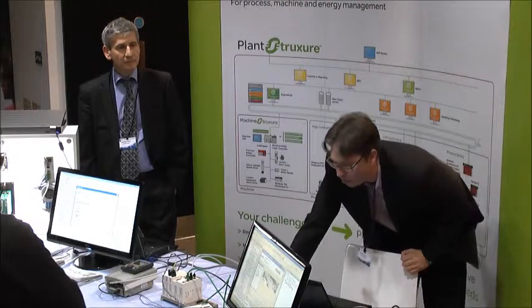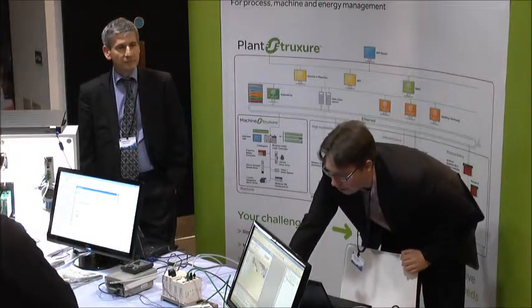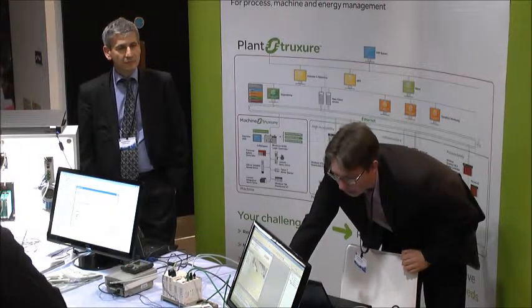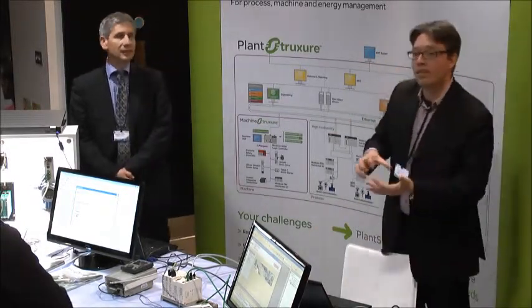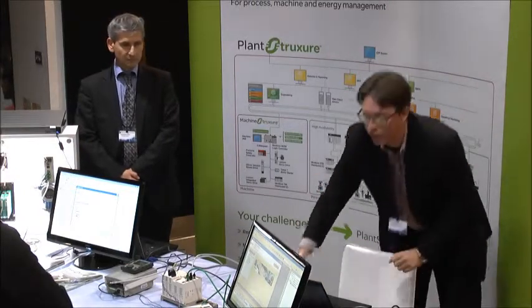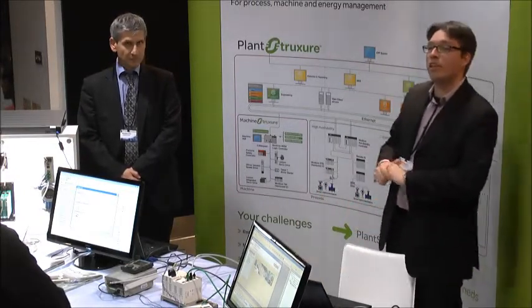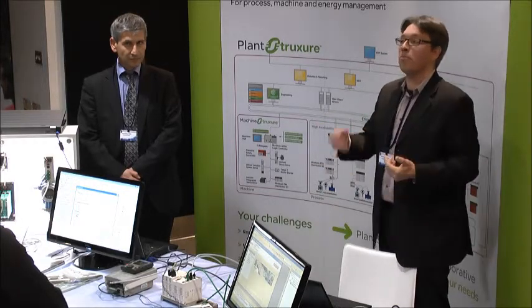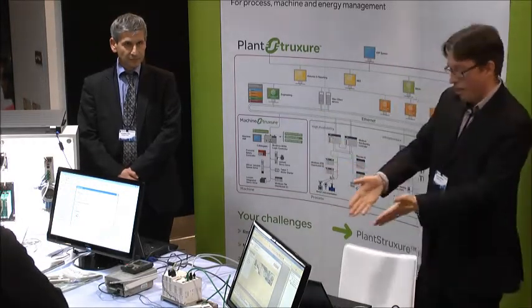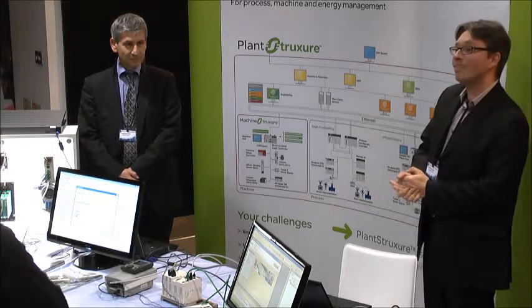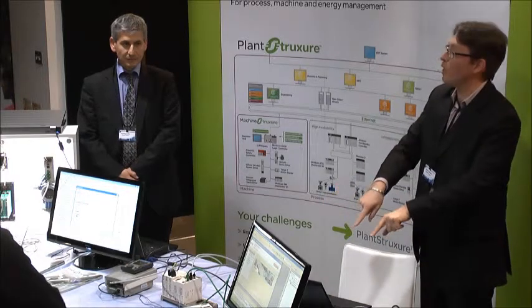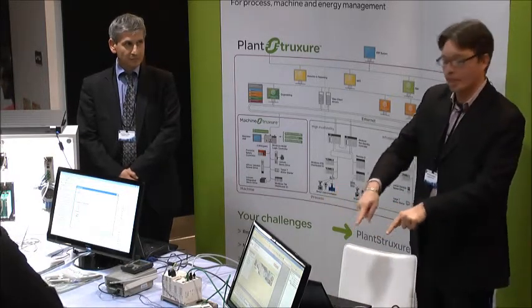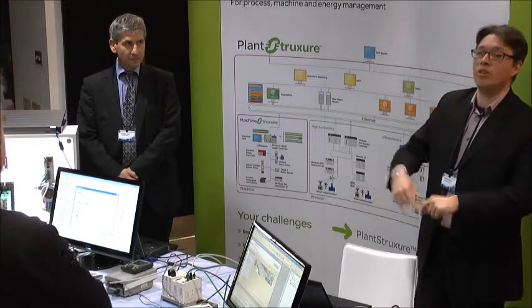and of course, if I double click in my software on the DTM, I have not the Schneider interface, but the user interface and the good functionality, parameters and diagnostic tool developed not by us, but by the manufacturer of the devices. And this manufacturer is Rotork. If you store the application, the parameters of this device will be stored in the same file with the configuration of my PLC.